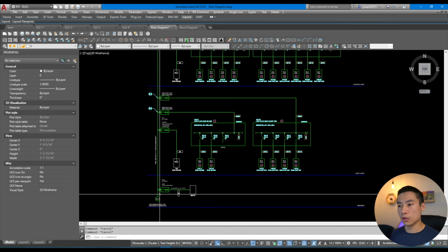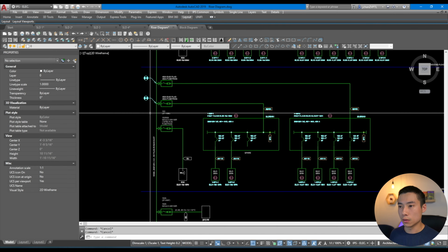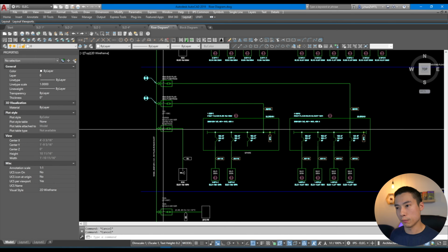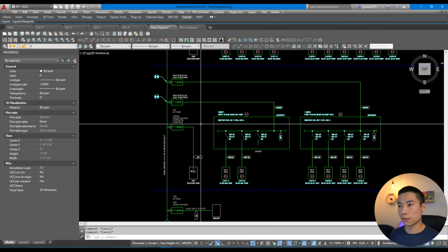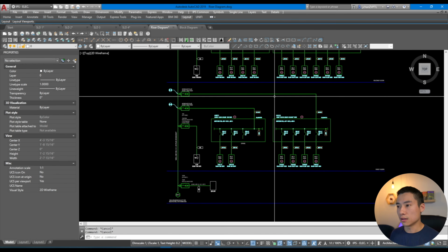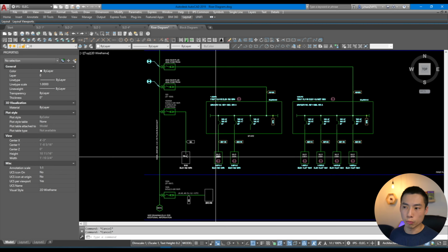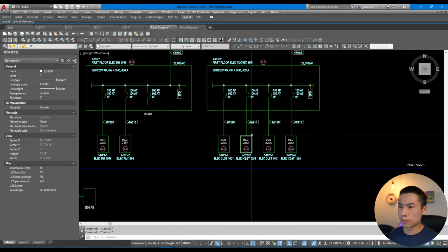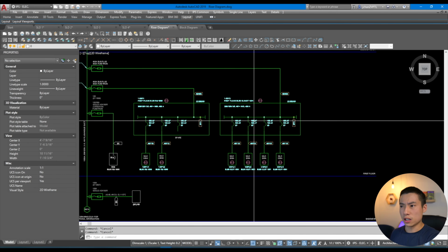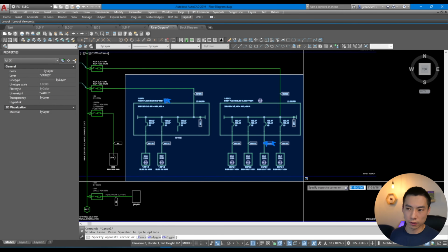And there you can show this running vertically, and we have it designed such that we have bus plugs in here going to panels and distribution boards. So from here you can see that the first floor has 2 distribution boards, and we have 2 branch panels out of each distribution board. This one has 4. So similar features here. From here on down looks like a single line diagram.